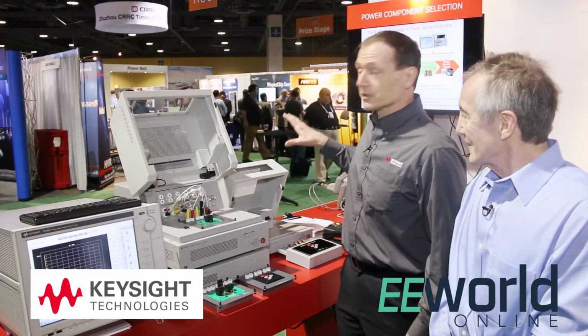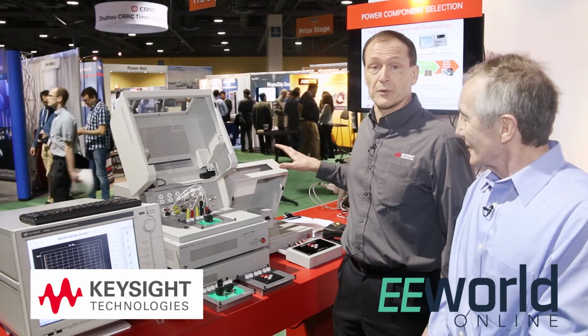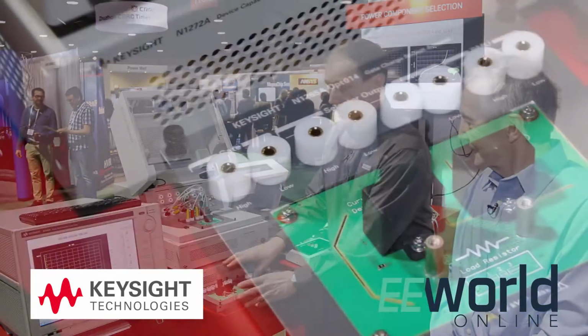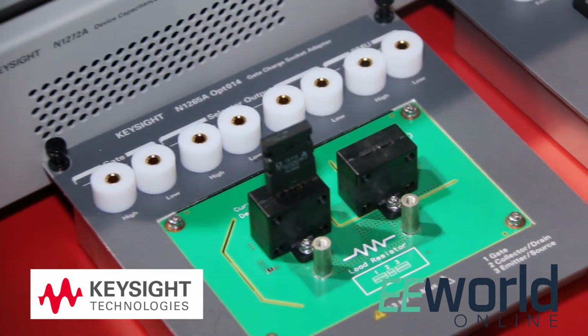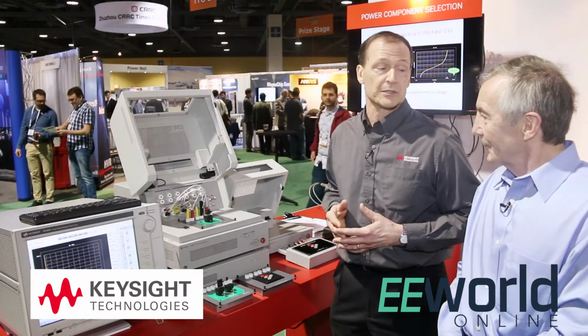And also it's PC based, so it's much easier to manipulate the data and do all kinds of post-processing, things like that. Also, unlike a curve tracer, we can actually measure capacitance up to 3000 volts. And we can also measure gate charge as well. So we can do complete device component characterization on a power device, which of course curve tracers can't do.